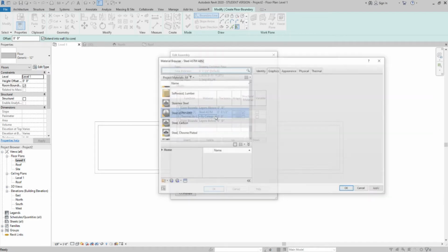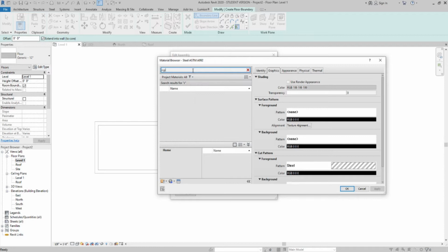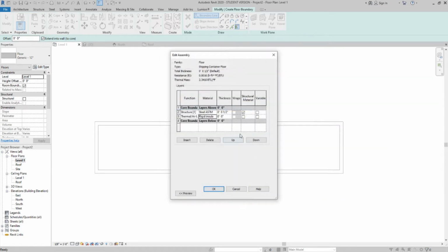Thermal, thickness is 4. Insert another one down. Substrate. Now here, you can do some furring strips. We could do a corrugated deck, some concrete. There's a couple things we can do here now that we have it insulated. What I'm going to do is furring strips, corrugated metal, and like a concrete finished floor. I think that would look kind of cool. However, you could do furring strips and like plywood and then a wood floor. You could go tile. It's kind of up to you.